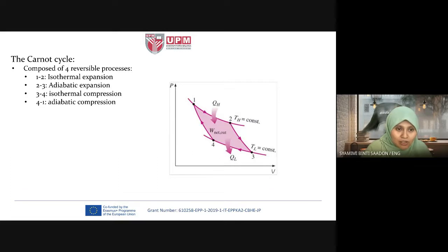We can sketch the process of the Carnot cycle in a PV diagram, pressure versus volume, not velocity. In the PV diagram we also have isothermal lines to indicate isothermal processes. First, 1 to 2, expansion, so pressure has to decrease, but at constant temperature, isothermal.